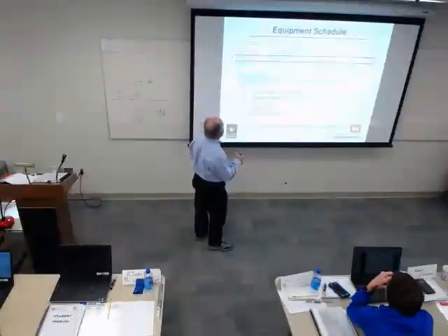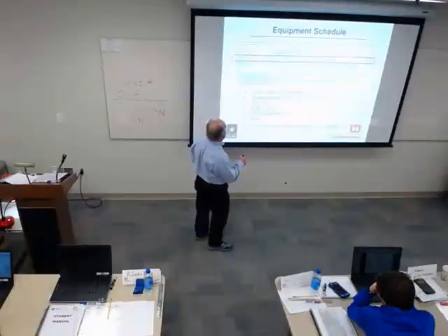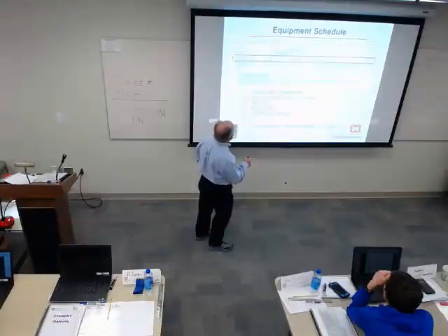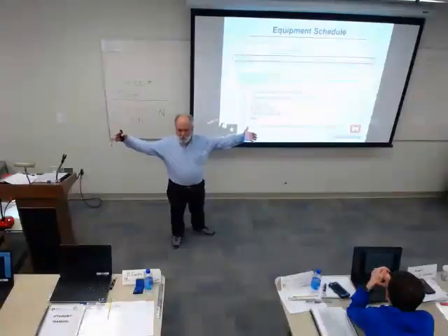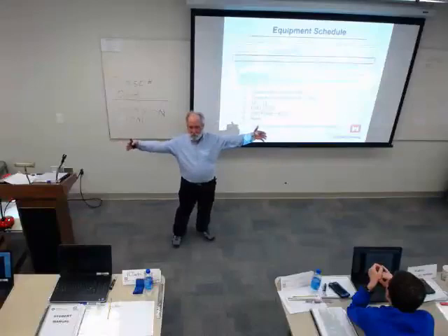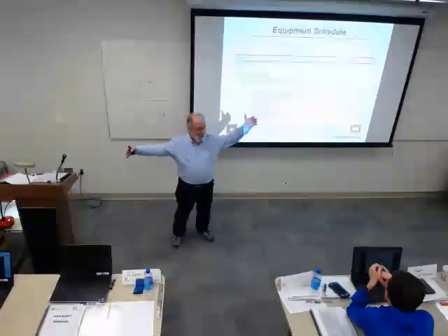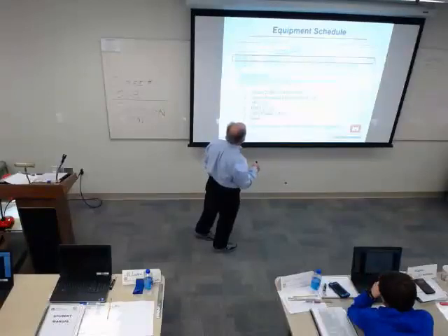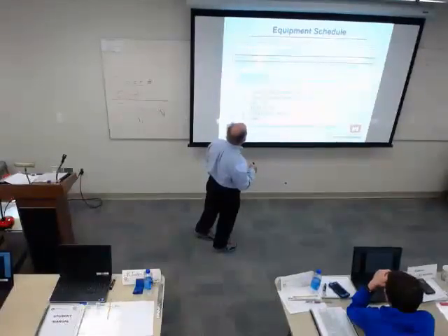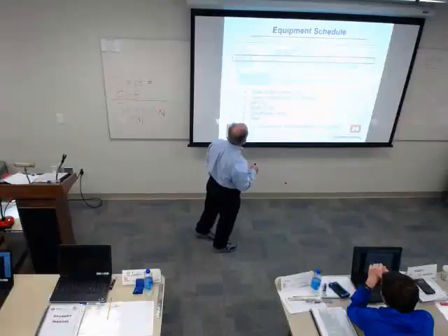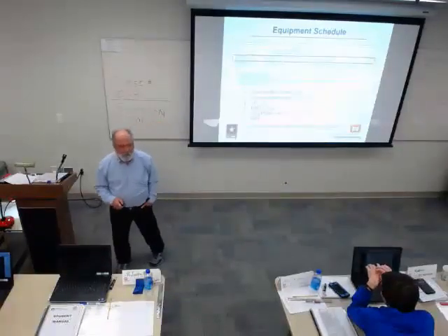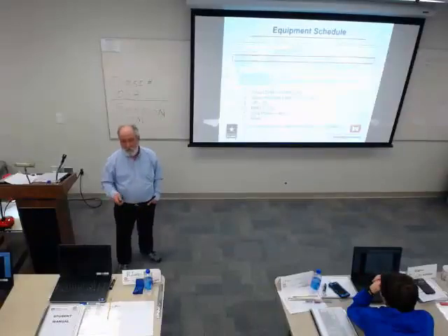That's the type of unit. This is a VAV fan application. CFM is 18,000. Entering the external pressure, that's the pressure outside of the unit. If we put taps on the outside of the unit on the intake side and on the discharge side, the difference across the unit is 2.75 inches. Total is 5.5. So in this particular case, over about half of our loss is just inside the unit.